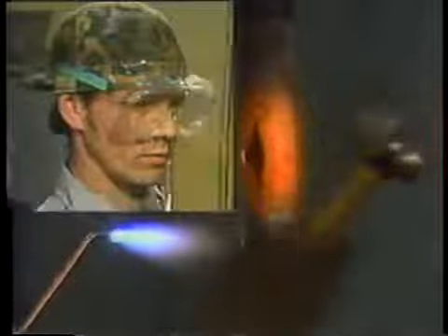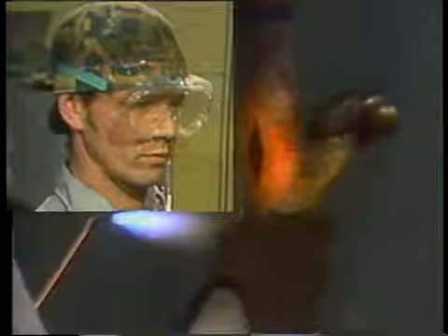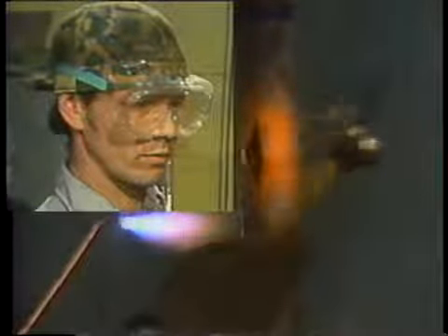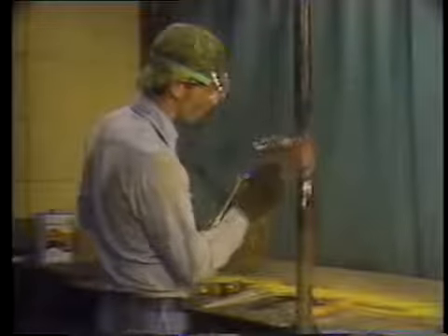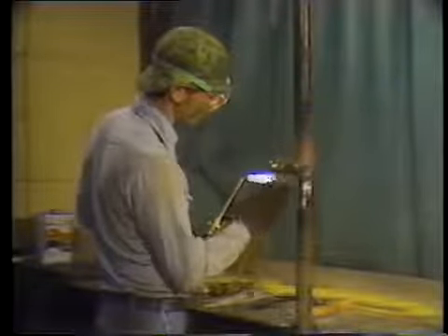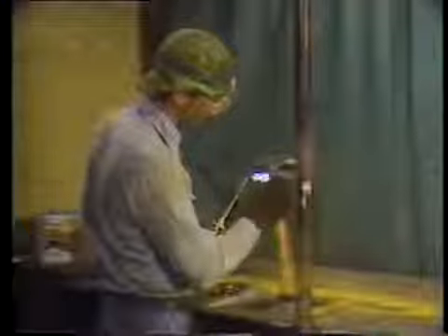Once the tube has been evenly heated, close the rupture by pounding the tube with a hammer. This forces the edges of the rupture back together. Eye protection must be worn when doing this because fragments of metal might fly off the tube. If the tube cools off before the edges of the rupture are close enough together, the heating and pounding process will have to be repeated. The edges should be forced as close together as possible, but they don't have to touch. Take care not to pound so hard that you dent the tube. That can restrict the flow inside.